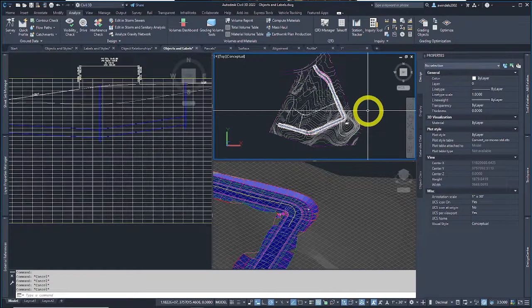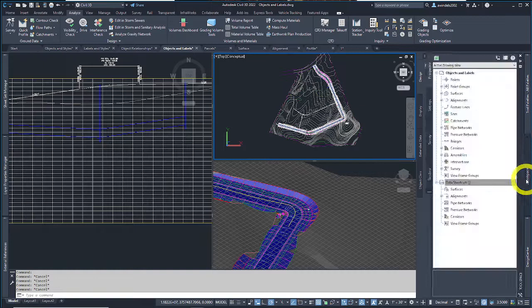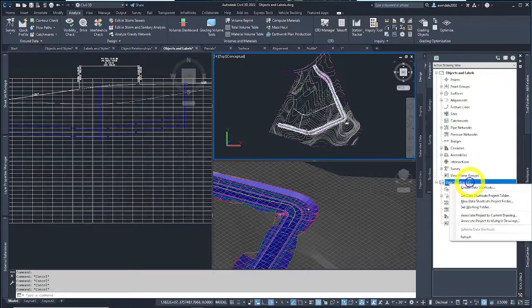When we create a shortcut, we make a data shortcuts project folder, which also will reside in tool space in here, and this will populate. This is a clunky process. It's one of the more confusing ones that every engineer has to ask me about. It's not that intuitive. It has a certain few steps to it. Let's see if I can bumble through at least the classroom example.